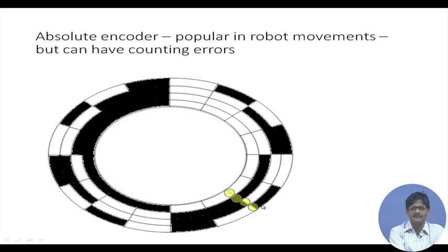For several nanoseconds, it might read 1, 0, 1, 1, because change has taken place here, but change is not taking place there, just because these are physical devices and they have their limitations. So, this change takes place a little late, and therefore it reads 1011, and that is a gross error, because it tells the machine that I have reached actually this position of the encoder at this particular angular line. So, these changes, if they are coming in pairs or more than that, might result in